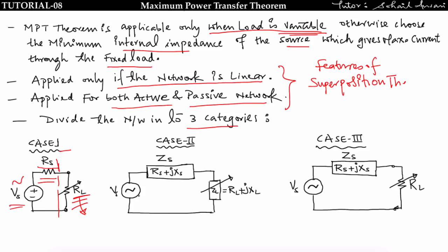Now see case 2. In case 2 we cannot use DC sources. Why? Because here impedance will come into the picture. Suppose in any complex AC circuit, we get VTH as the voltage source; we can reduce that complex AC circuit into VTH and ZS, the series impedance, which consists of resistance and reactance both.